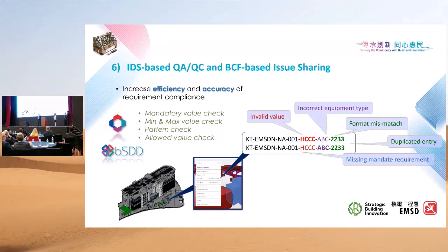With that, we have tried it out using our headquarters BIM, and you can see here, it was used to validate with various market-available IDS checkers. Our building consists of 15 IFC files with more than 37,000 E&M assets. And we have proven that rather than using days for checking, this automation requires less than half an hour to go through very complex, comprehensive checking and generate all the outstanding issues in a BCF file for further review and rectification. So the project team's handover to us will be more swift.